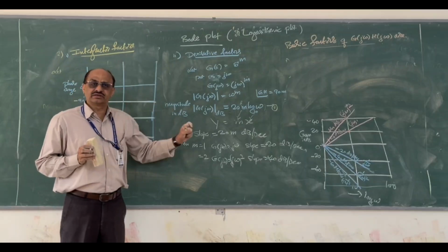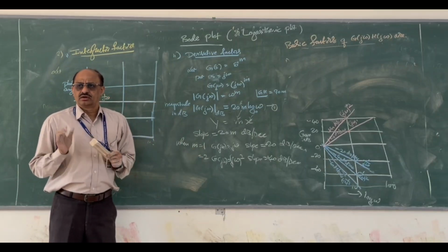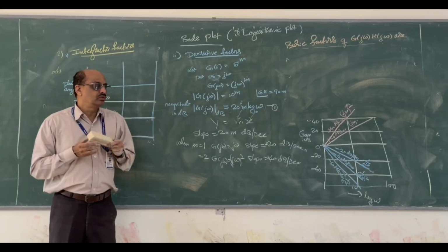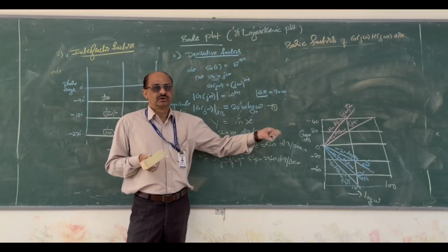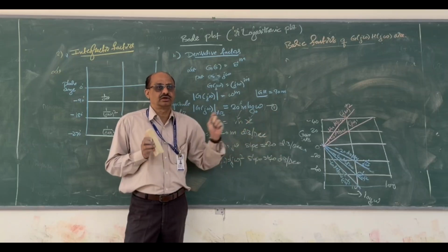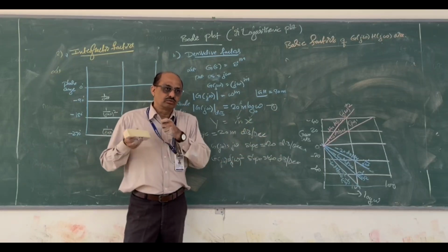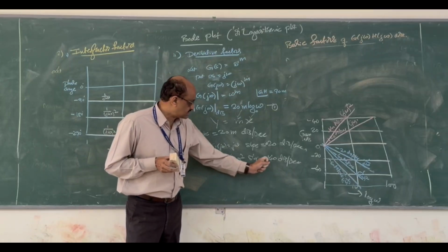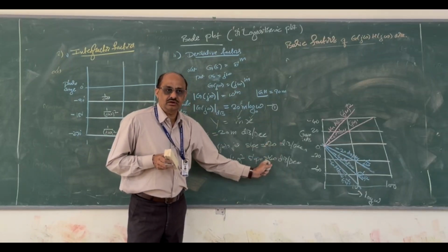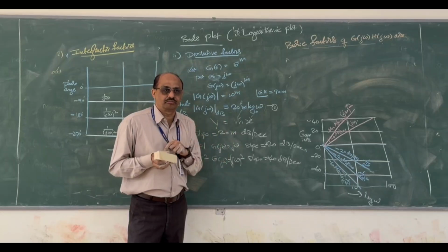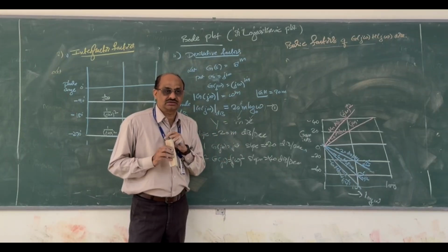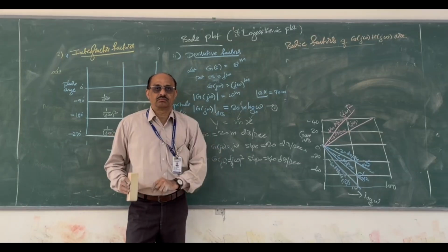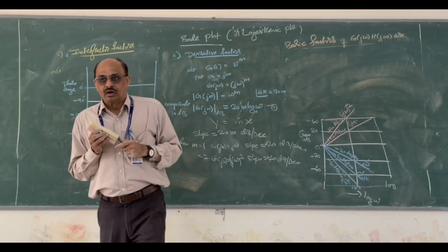Need to remember, very simple. Need to remember just the slope, and then it gives you a straight line. You need to plot that together; how to plot, we will see. So at last you need to remember only this: plus 20, plus 40 if I have 1 zero, 2 zeros; 1 pole minus 20, 2 poles minus 40. That's all.